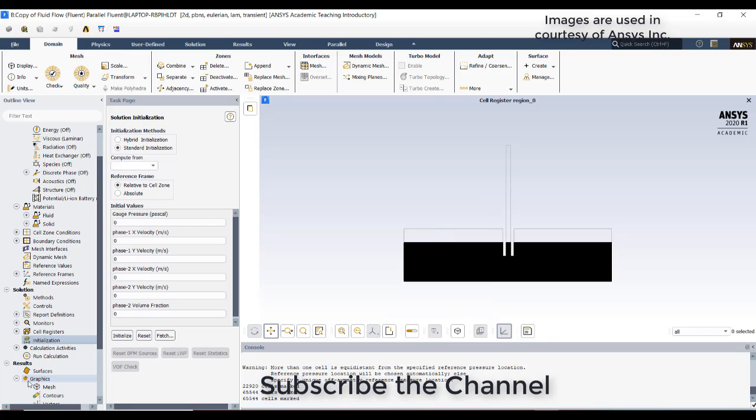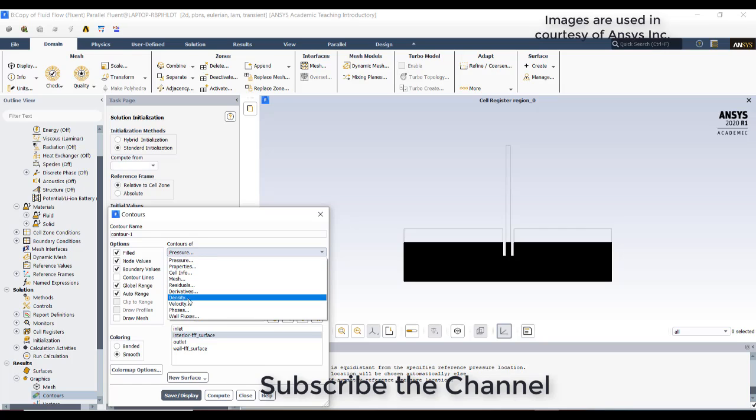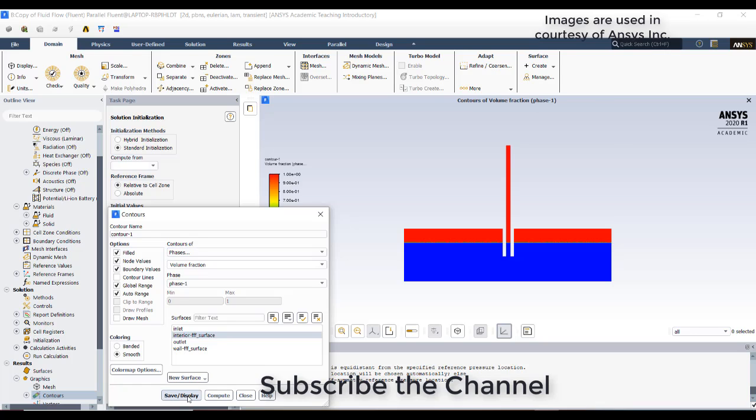Just check for your confirmation. Go to contours, click on interior surfaces, faces. You can leave that. Save display. So you can see air is at the top and water is the bottom one.